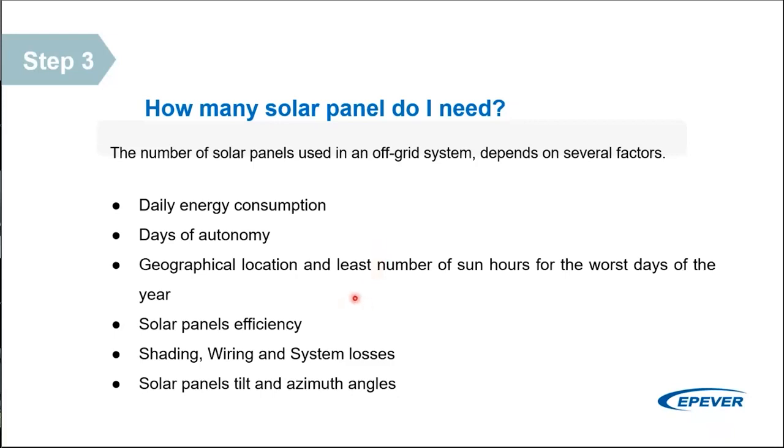The sunlight intensity and ambient temperature are the two parameters which affect the power produced by solar arrays. The solar array voltage does not change much at different irradiance levels or inclination angles, but the current output is proportional to the amount of sunlight falling onto the array. Also, temperature decreases the generated power of a solar array. That's why sometimes you have a power loss because of high temperatures. Depending on the properties of the semiconductor material, the temperature rating might be different in different panels. It could be monocrystalline, polycrystalline, different kinds of solar panels.